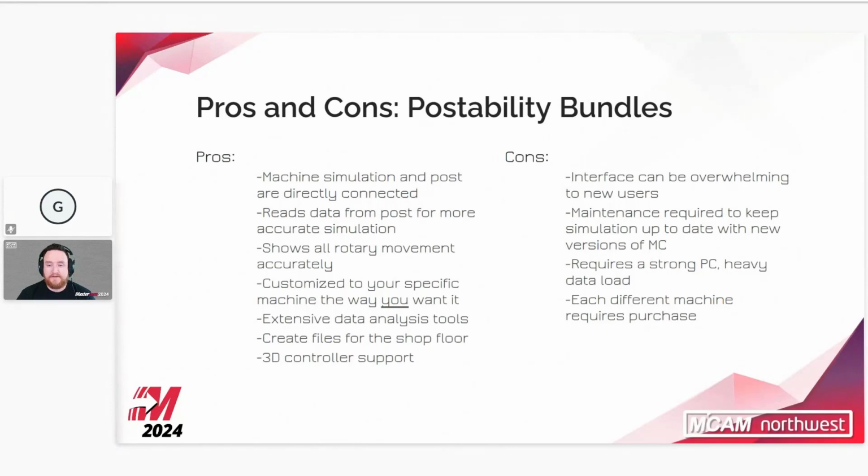Additionally, all of these bundles can be customized exactly the way that you want. So if your machine has a particular set of funky parameter setup that makes it behave differently than any other machine of the same make and model, that's okay. We can make sure that the post and simulation works correctly for that machine by working with Postability, because they're very good at this. It's what they do.